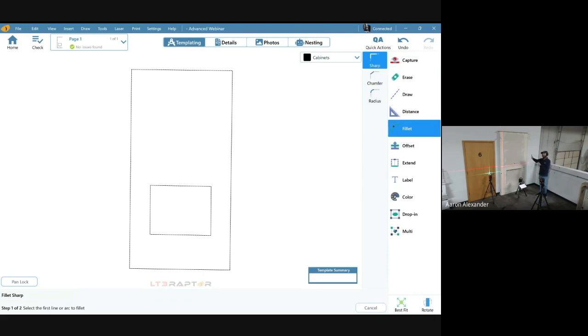The reason why we're using this laser and projecting level and plumb onto here is to see how level and plumb this edge is in space. And also we're going to figure out how plumb this edge is in space. Also, we can tell the firebox as well. So that's the power of the Lino here. I'm going to set this up right out here in front of me on the wall.